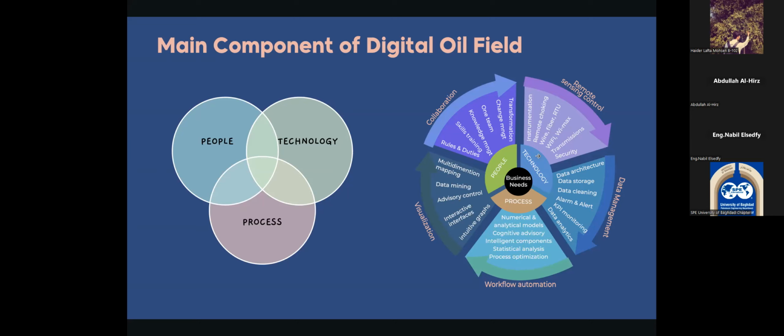So you need a filtration system to filter that data, so it can give you exactly what the wellhead temperature is, by excluding the effect of the outside temperature, whether it is day or night. So you can set up an algorithm or workflow to filter that data.